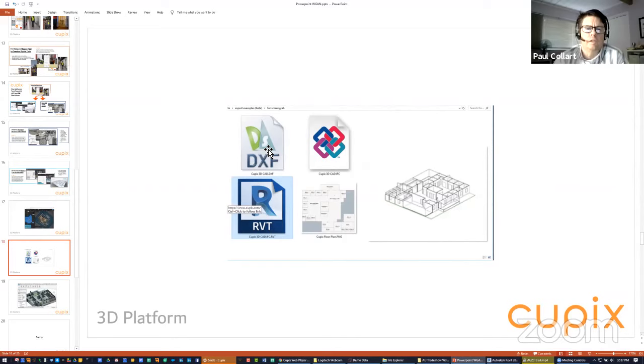We also support the export of what's called an IFC, which stands for Industry Foundation Classes. Think of it as a generic BIM exchange format. Either one of those, depending on what you're looking for. If you are working with a BIM application like Revit or ArchiCAD, you'll want that IFC because it maintains the intelligence of those objects. It's the gold standard for interchange file exchange. It's exactly what you want to move files around. Would you agree with that? Yeah, for BIM models, yes. Gold standard, exactly what you need for bringing into Revit, ArchiCAD.